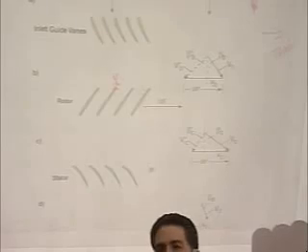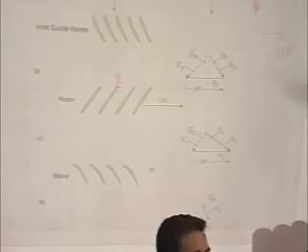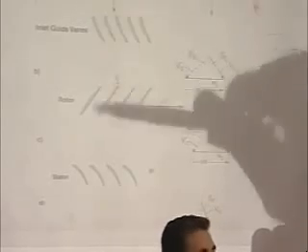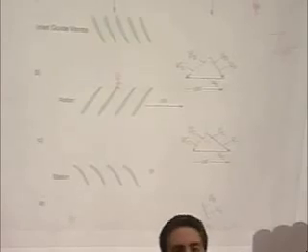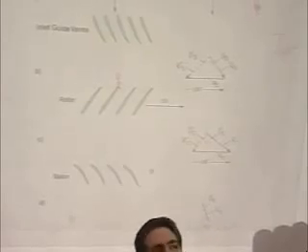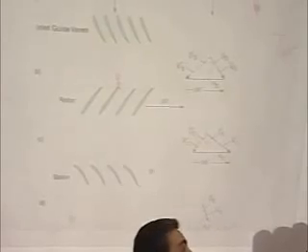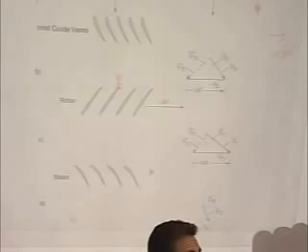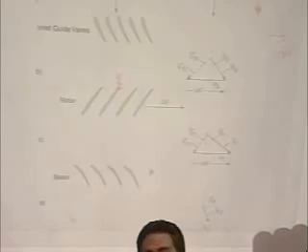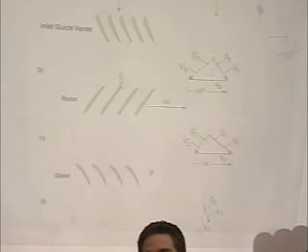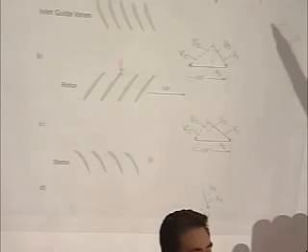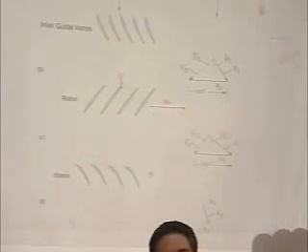And I warned you about this. The way you have to solve these problems is you go from stationary to rotating frame to stationary frame to rotating frame to stationary frame to rotating frame. So you have to do a transformation between those frames, between each and every blade row. Now luckily there's only one difference between the frames, and that's that one has tangential velocity, the other doesn't.